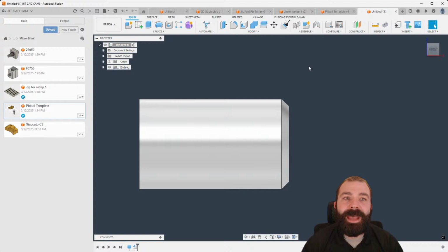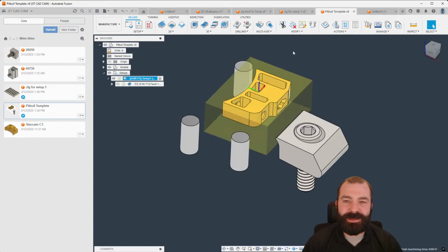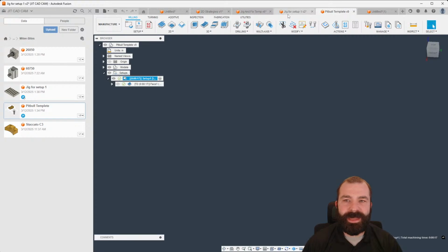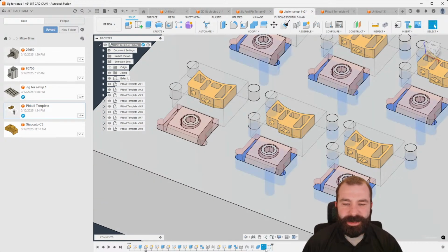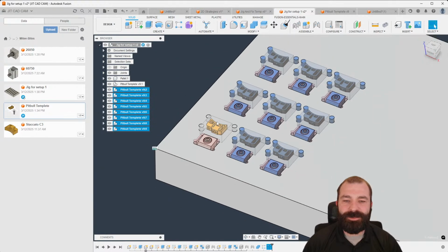So you would have to do two separate patterns. Yes, Elijah. But this is where it gets a little tricky when we talk about setting up those jigs and fixtures. I did one pattern for the pocket and then a separate pattern for basically my Mighty Bite assembly I brought in.